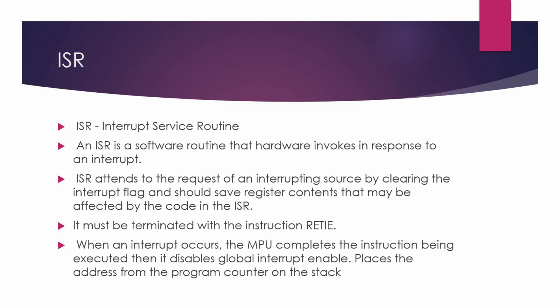When an interrupt occurs, the MPU completes the instruction being executed. That is, it disables the global interrupt enable and places the address from the program counter on the stack.